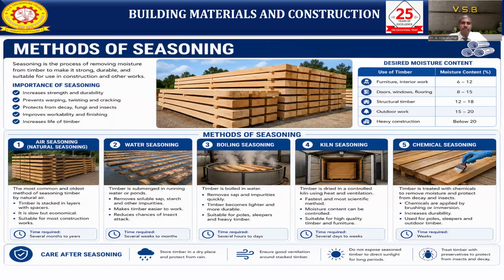And water seasoning: we keep all the timber waterlogged, in running water or a pond. It removes the soluble sap, starch and other impurities, apart from the moisture. This makes the timber easy to work and reduces the chances of insect attack. This takes several weeks to a month, but the only thing is we need running water for the moisture to be removed.